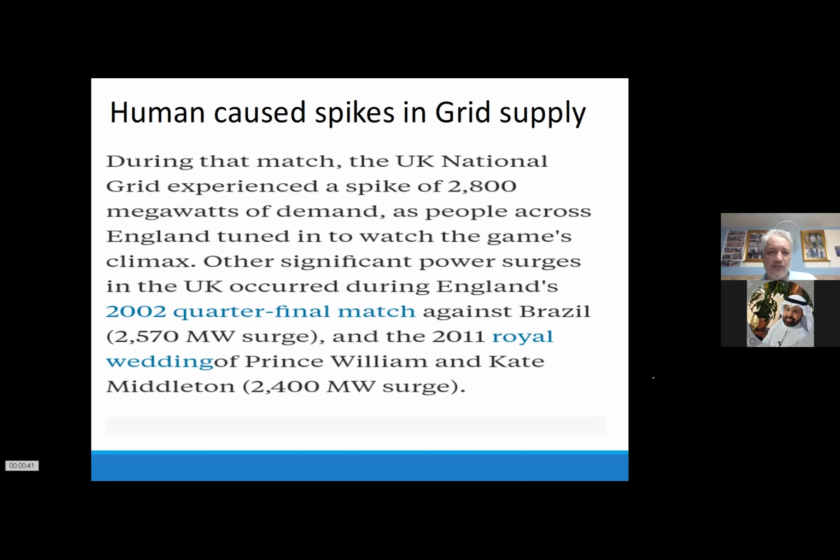If you make temperature zone installations like I prefer, then you always have similar conditions, because it could be that the first module has like 50 degrees and then carries the heat on to the next and the next. I saw roofs installed with 10 or 15 strings, so the whole roof was covered with modules, no breathing, no walkways in between. That has changed already. But if you don't do it this way, you must imagine you have between 15 and 25 degrees difference from the string at the bottom to the string at the top.